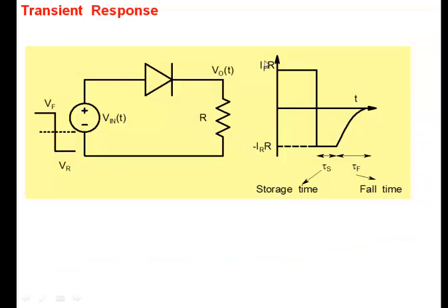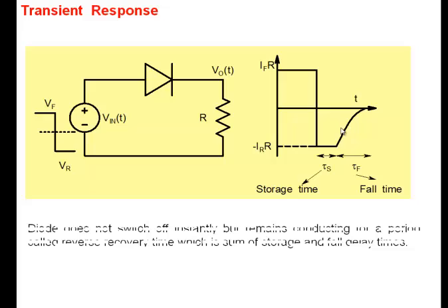Alright, so this is showing you what happens in a diode here. If you switch, the diode will conduct for a certain time in the reverse direction and then switch off here. So it takes some time for a diode to switch off. And that is what is responsible for the diode conducting large current in the reverse direction here. Okay. So that's an important point.